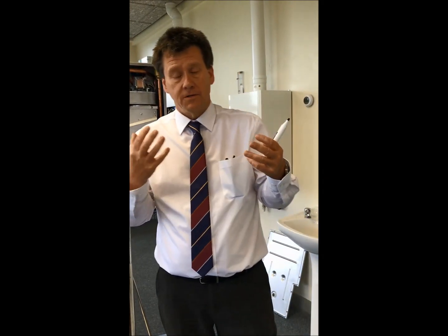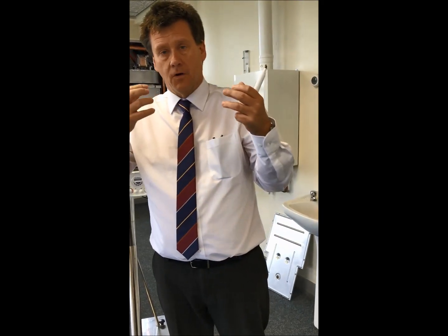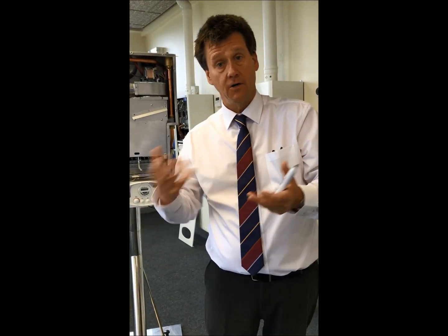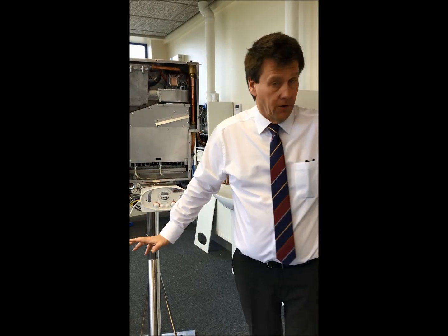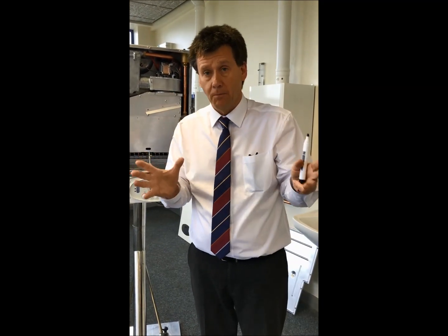What we must get into as mindset, guys, is understanding the sequence, okay? Understand the sequence and understand the standard of a gas boiler. The sequence on gas boilers is virtually the same, because they all go through the same test house to get to the end sequence. So if we switch a boiler on, then the first component to energize is the pump.